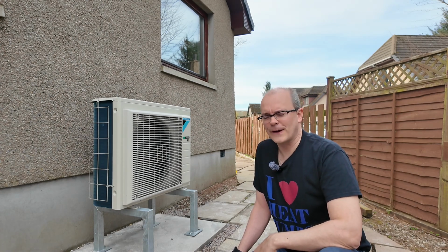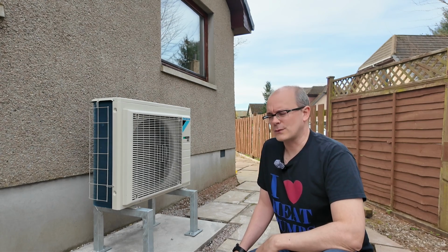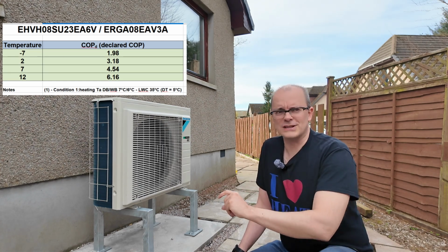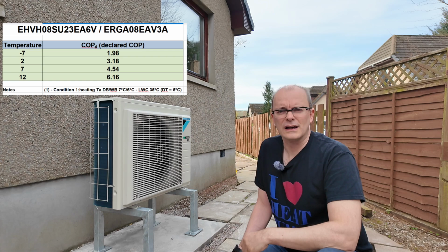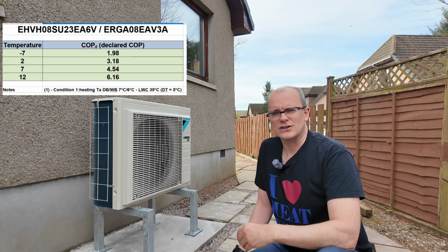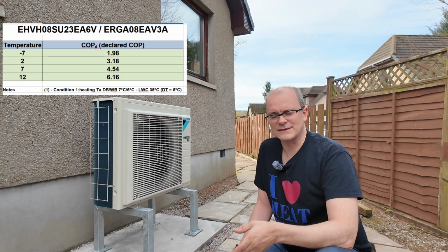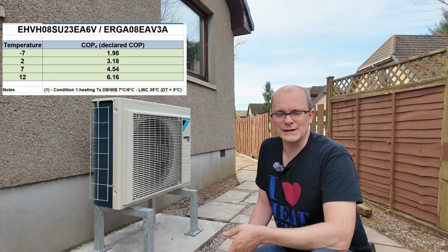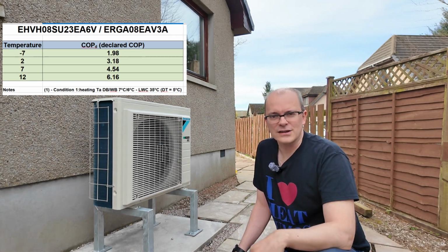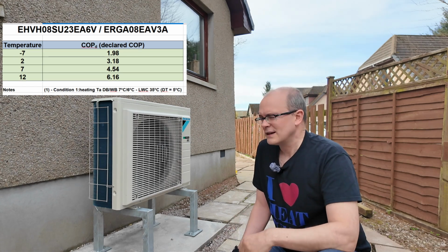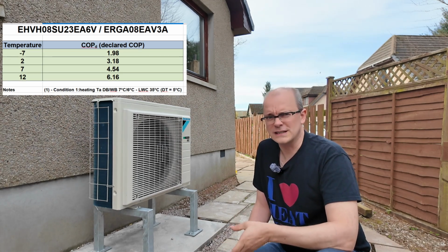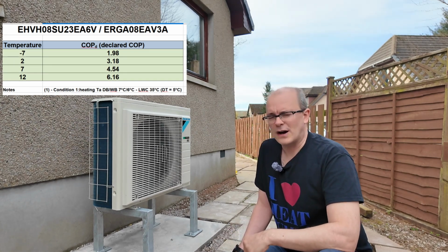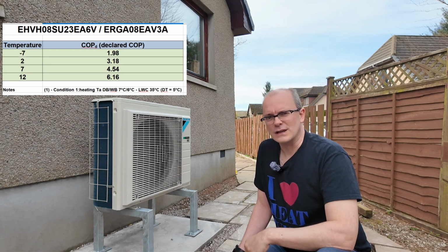But I've also got some further ideas on how to develop this tool. One of the things I want to do is compare the actual coefficient of performance with the published coefficient of performance for a particular ambient temperature. As I've shown on that table, we do have two sets of data. We've got one set of data with a flow temperature of 35 degrees, another set of data with 55 degrees, and I can extrapolate and interpolate that data to get theoretical coefficients of performance for 30 degrees or 28 degrees, or interpolate in between those two temperatures. I want to try and put that in, and I need to do a little bit of thinking in order to do that.